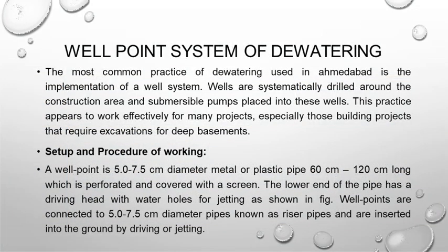Next system is the well point system of dewatering. The most common practice of dewatering used in Ahmedabad is the implementation of a well system. Wells are systematically drilled around the construction area and submersible pumps are placed into these wells. This practice appears to work effectively for many projects, especially building projects.